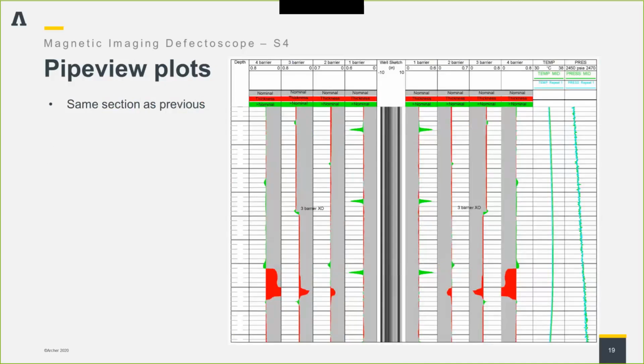Yeah, I mean, it needs to be a magnetic and conductive deposit on there. Mostly what we will see are the collars. But if there are some slight areas where it seems more than nominal, that's generally accounted for by the variation in manufacture, because the casing OD is specified as 13 3/8 or whatever, plus or minus a little bit, and the thickness is also specified with a plus or minus tolerance on it.